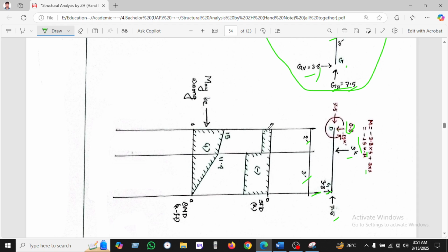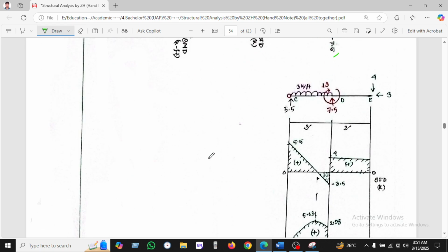So now we'll calculate here. We've seen that 8 is given downward, and this 3 is downward, and 3.8 is upward. We're starting from the left side. When we take the 13 here for the shear force diagram, the moment 13 is given upward and the shear force is downward. That's why it will be negative, minus, in calculating all the values here.